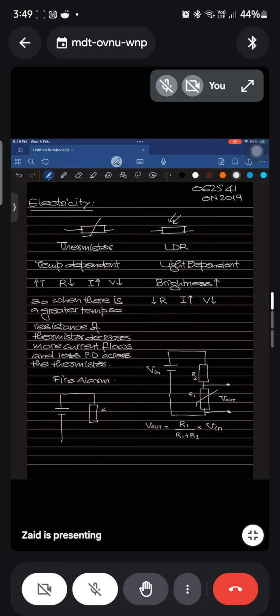The fixed resistor is 4 kilo ohms, and you've got a thermistor that is around 3 kilo ohms. If you have placed the potential divider over here, the input voltage is, let's suppose, 100 volts. You need to find the value of V out. You can cancel out the kilo because they are the same units. Just let me know what we are getting quickly.